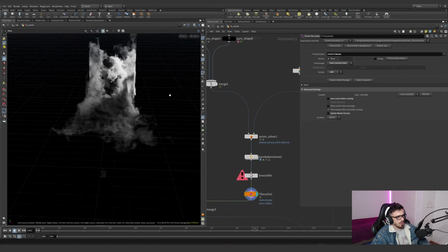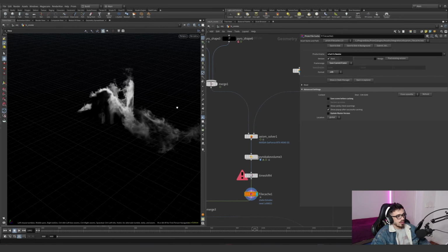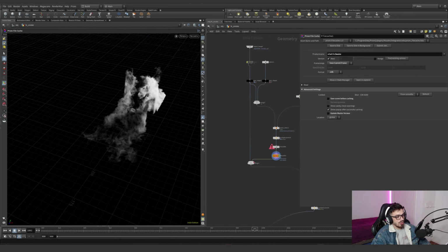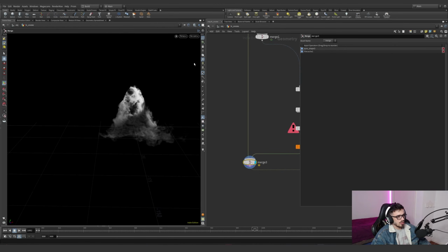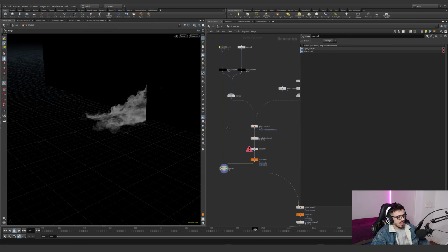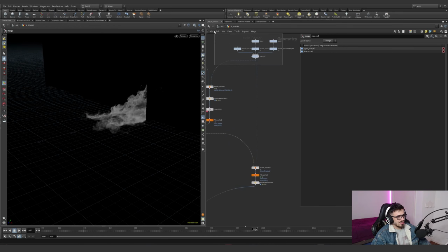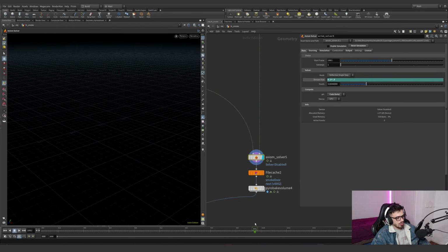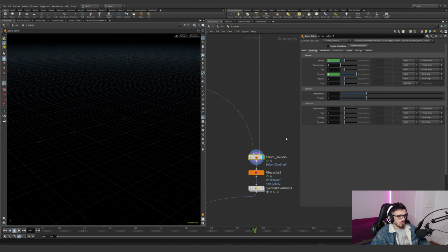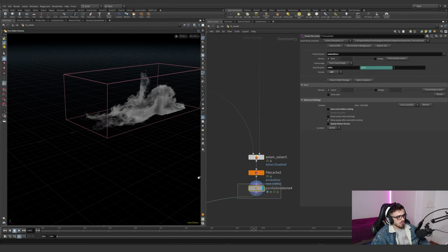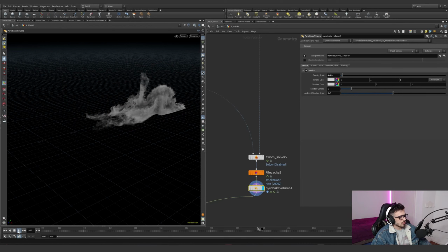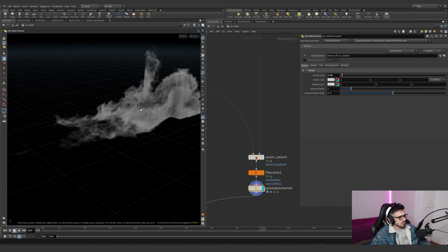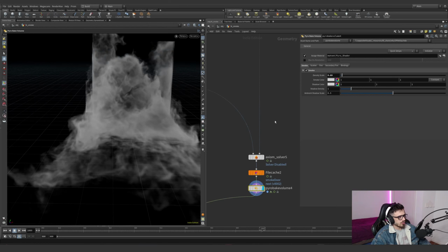What I'm going to be doing is time shifting this simulation. So this is the frame I liked. This is what I want to have. This is a really nice trick because now that I have this shape, and again with the collider, what I can do is use the same shapes and do a new and better simulation starting on frame 1001, animating the cache so it reads only for one frame with velocity, and look at how this looks with even more resolution. Let's press play. See, it's moving a little bit, but it's staying overall where I want this to be.